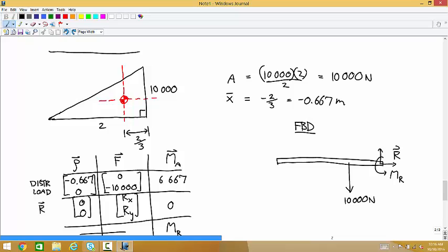Okay, let's do another one. Yes? What would happen if the triangle split, where the larger amount of force was on the end? Like in the real world, I'm thinking that's how you would break it off the wall, right? Does it change the moment then? Yeah, the moment would change, and the effect would be the centroid of that triangle would be in a different place. So you'd go through these same steps, calculate where the centroid is, but now you'd just be applying those forces at a different spot.